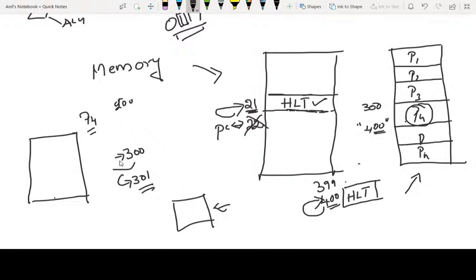So what we do is, the final instruction will be written. It's nothing but a halt instruction. When the halt instruction gets executed, the program counter will be repeatedly updated to 300. What is halt? Halt will be realized by using one instruction called branch unconditionally to the same location, BUN 300.